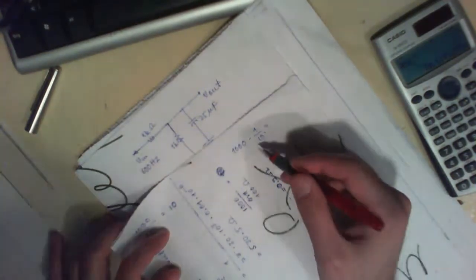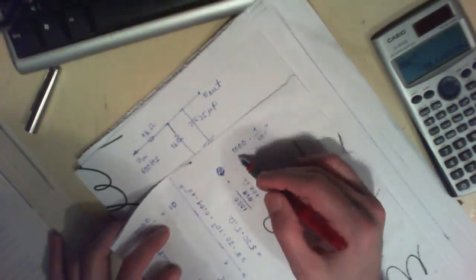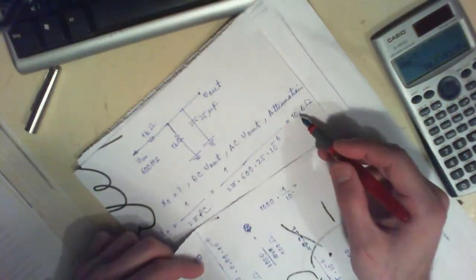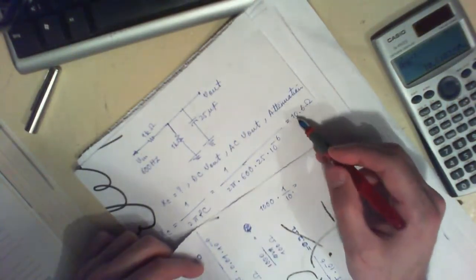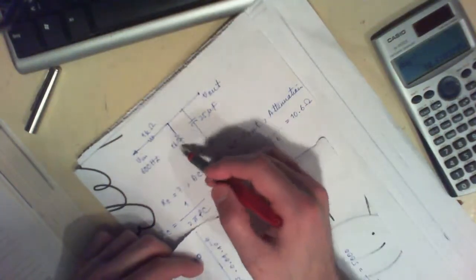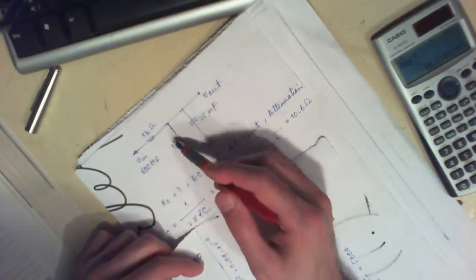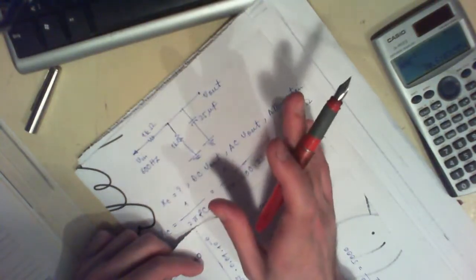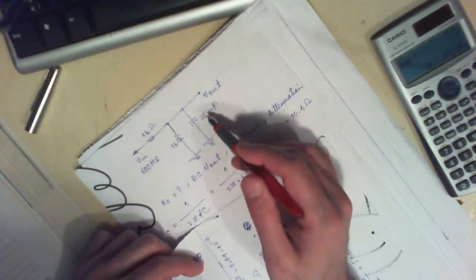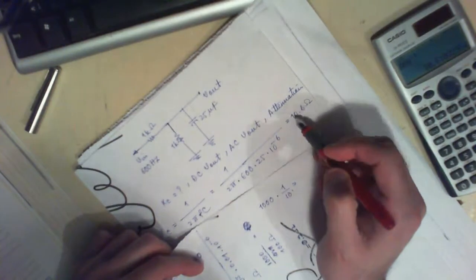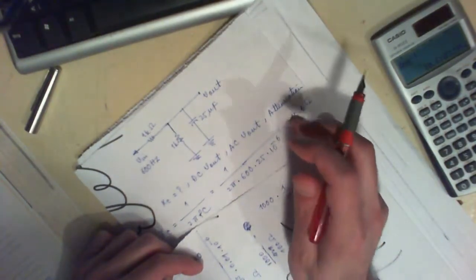Actually, 10 ohm is very close to 1/100th of 1 kilo ohm, that's what confused me. If you can go down to at least 1/10, then of course you can go ahead and do the simplification, meaning that if the reactance here was even 100 ohm, then you could do it.